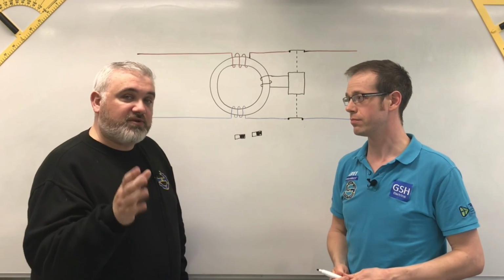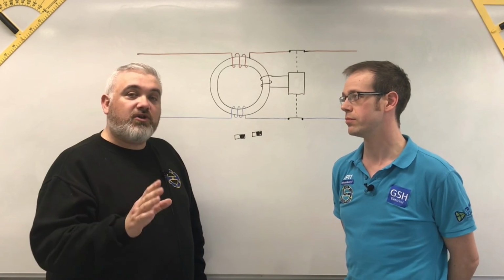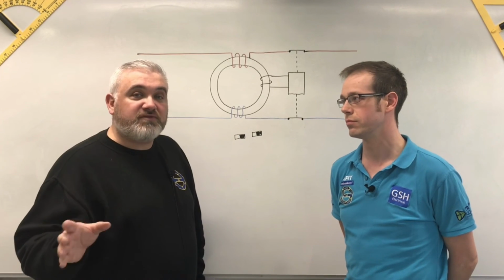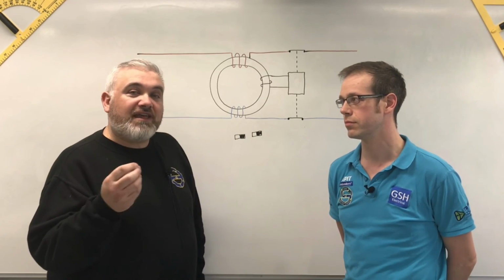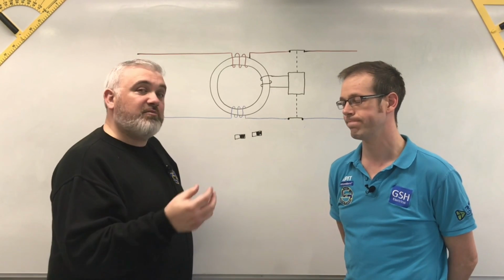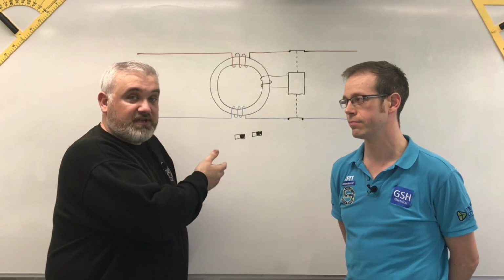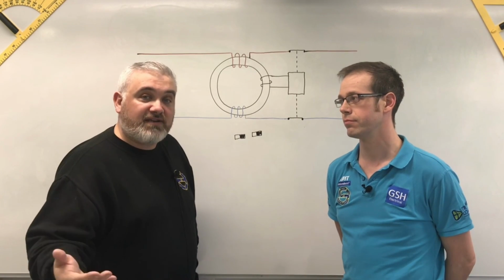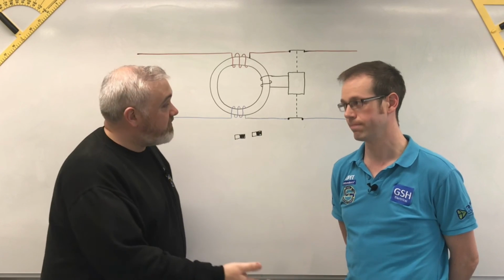Now, a lot of you will be watching thinking, but I have AC type RCDs, are they all dangerous? No, not necessarily. However, what you need to be mindful of is the connected loads within the installation. Because they're microelectronics and power electronics, they can saturate, they can leak, they can perform in a way which we're not used to. Hence, they can perform in a way which can affect connected components of the electrical installation. Now, as this knowledge grows, the knowledge of how we select and erect and the wiring regulations changes to inform us accordingly. Hence this video today.